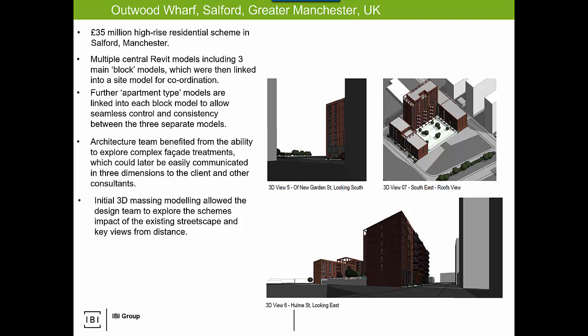Depending on Revit, Vectorworks, ArchiCAD, EcoSim, etc., there are different technological capabilities relative to how to split models. But fundamentally, regardless of what software is being used, a project like this very easily lends itself to three main building models that all come together on a site. It's very logical. Depending on the size and complexity, you may divide the models, maybe divide them in the middle. I don't know. There's nothing right, nothing wrong. You may get exposed to software limitations that have to be explored. But at the end of the day, if this whole project was one big monster model, that wouldn't be good.